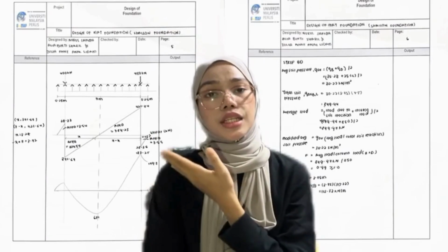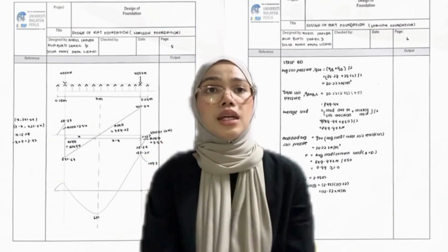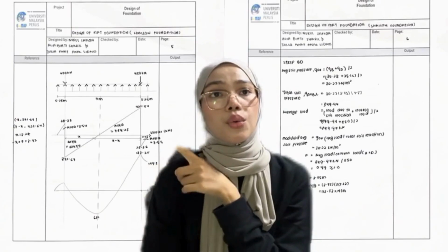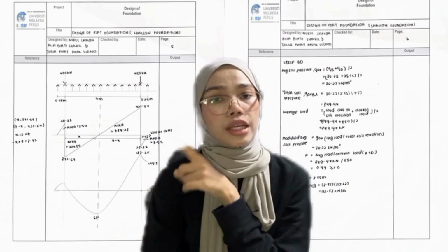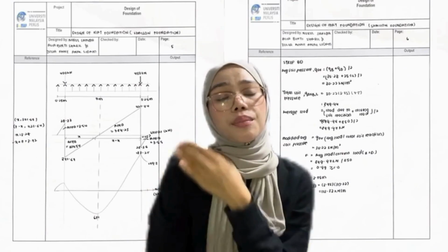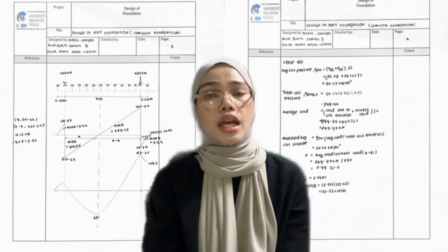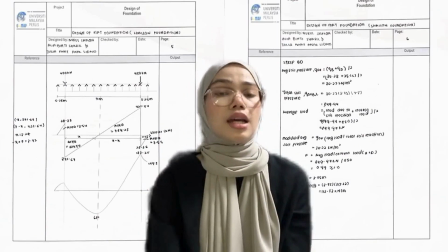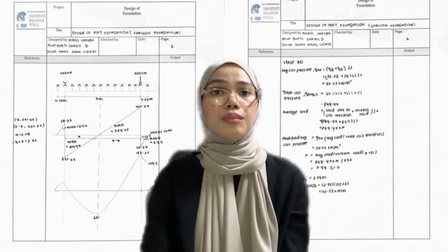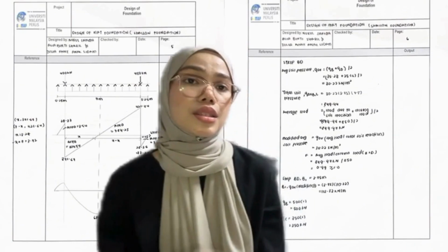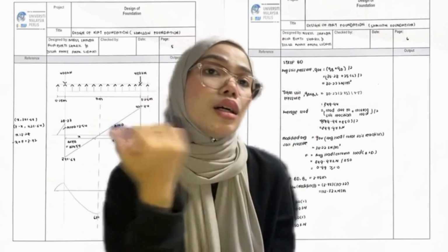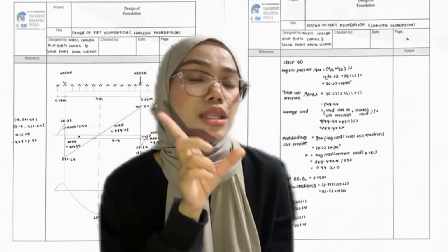This is the shear and moment diagram. The maximum moment is first 183.25 kilonewton meter at the positive point, and at the negative point it is 681 kilonewton meter. For strip BD, we calculate the same steps as strip AC